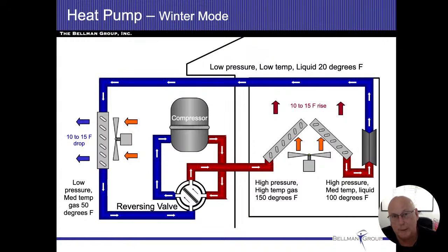So if I'm 70 degrees in the house, that means the air flowing out of there is going to be between 80 and 85 degrees. So if I look at my ductwork, the air that's going to be coming out of my ductwork is going to be about 80 to 85 degrees, all right? As that's happening, I put my hand on it and I feel it. Well, my body temperature is 98.6 degrees. So if I'm 98 and that airflow is 80, that's actually going to feel cool to the touch as the air that's coming over me. So I'm going to feel like I got cold air that's blowing out of the ductwork, when in fact it's actually heating my house, all right? So it's a little bit awkward when you see these things run.